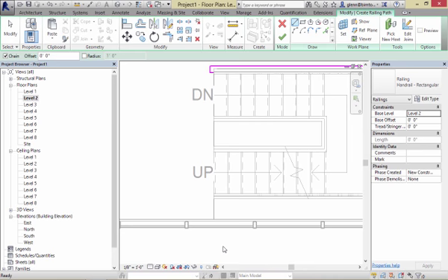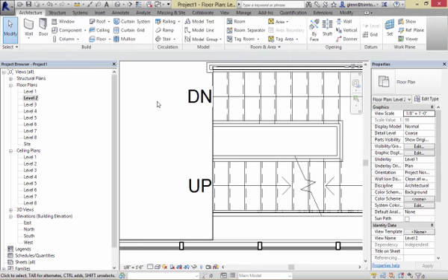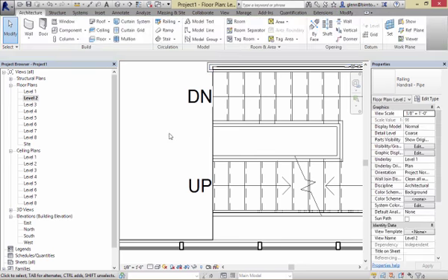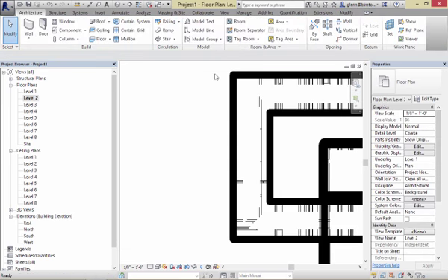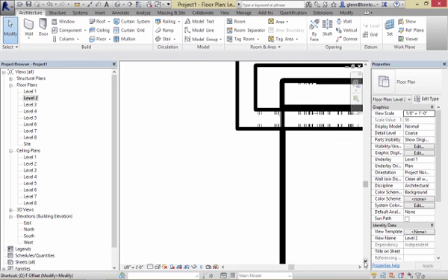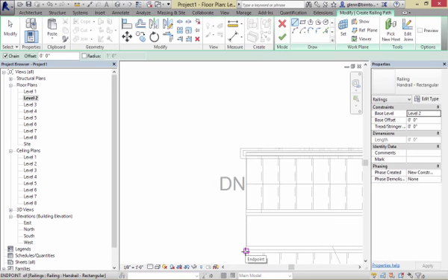I need one over here on the side. So you can't kind of come in. Since I only can draw single segments at a time, even though I would love to do the other one, I really just have to close that one out first. Let me change that to the pipe rail. Okay, you'll see this one actually did align. Go figure. I still need a little bit of rail between those two different stair sections. Let me zoom out a little. So between this section and that section, I need a railing in there. And I'll just do it from the center here, over to the center there.